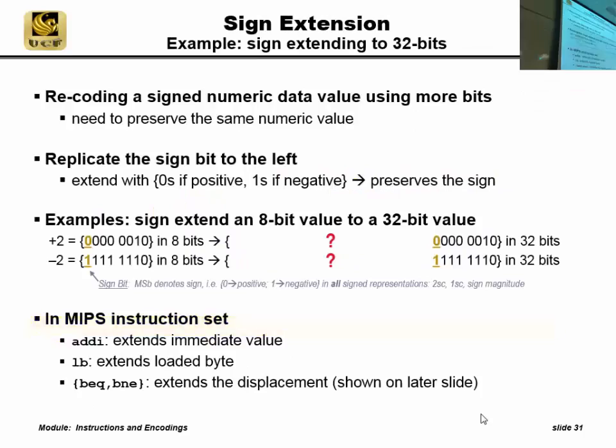Yeah, it makes sense. So, why did I spend all the time? Because I said we need to know number representation. We use 2's complement because, more than anything else, it makes the circuit really simple to design. We're going to see that. With the 2's complement representation, we don't have to have a special negative handling circuit. We just add them as if they're positive numbers, and the sign automatically, magically appears.